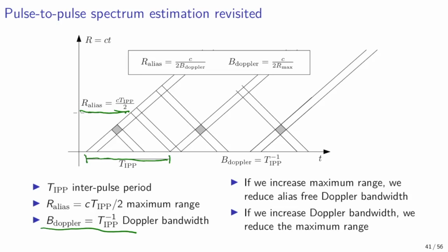For example, consider a radar target at this range. A radar echo from this range, corresponding to the first radar transmit pulse, will arrive simultaneously with the radar echo from the lower range, corresponding to the next radar pulse that was sent out. If we use the same radar transmit signal for each pulse, we have no way of determining the true range of the radar echo in this case. It could be either R0 or R1.